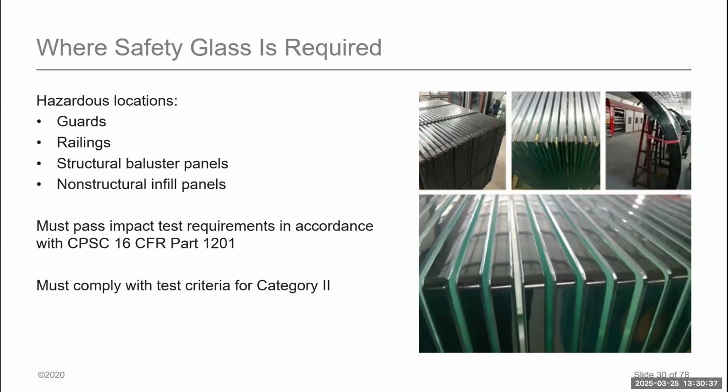Well, with no questions, we'll move into glass, and we'll talk about glass in detail here. First of all, when we do have guardrails, we do have to incorporate safety glass. Now, the safety glass itself will be tested by the plate glass manufacturer. Those are the manufacturers out there in the market that manufacture the single piece of plate glass. When we are talking guardrails, we will introduce into the chain of supply what we call a glass fabricator.